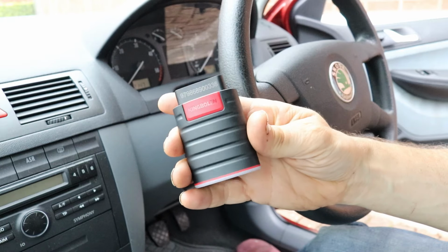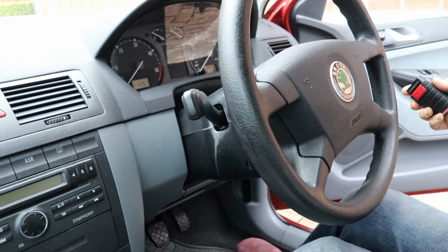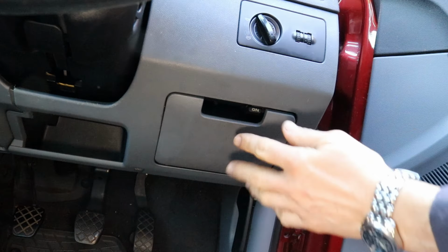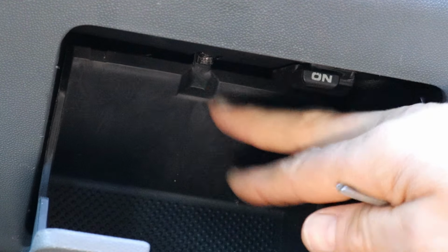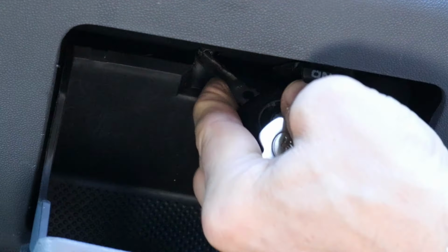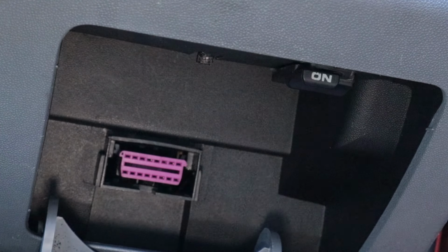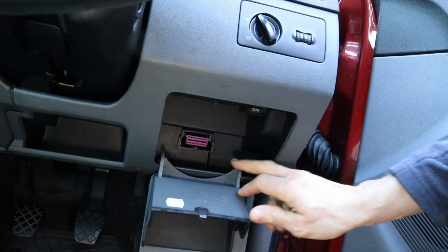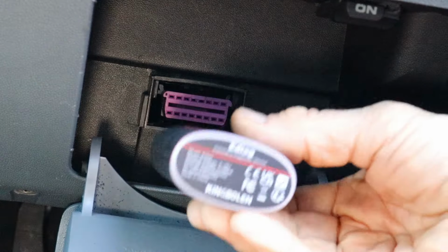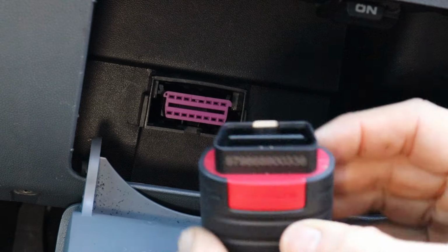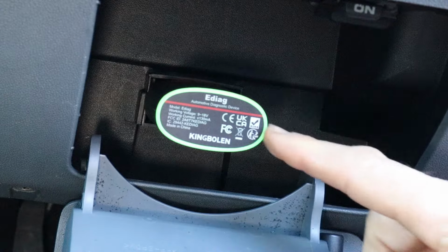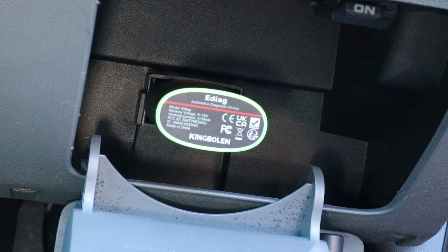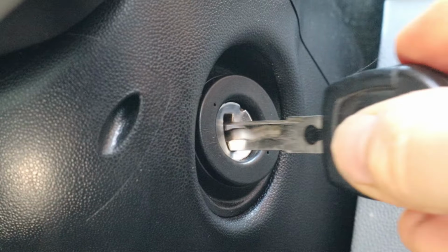And on the Fabia, it's behind the little cubby hole by the driver's seat. You just have to pull it forward. Then there's a little tab at the back that you need to press in so it'll open up fully. Past the catch. And it'll reveal the OBD port. Plug the device in quite firmly, obviously checking the orientation so the pins marry up. It'll click eventually into place so it doesn't fall out, which is quite handy. Once power's attached, it'll light up green around the rim. And we can do some diagnostics.